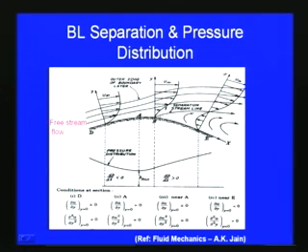at this location S. Before that, for example at A, we can identify a section where the pressure P is minimum. At this location A the velocity keeps on reducing like this, and the gradient of the velocity del u by del y will be greater than 0, and del square u by del y square will be almost 0, since the pressure is P minimum. So at this section A, del square u by del y square will be 0.